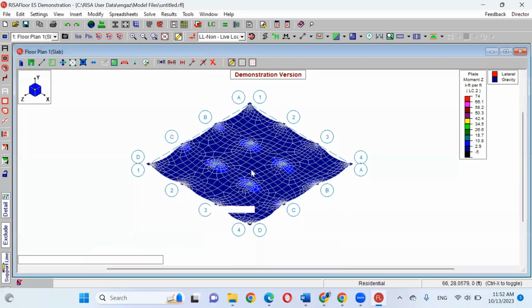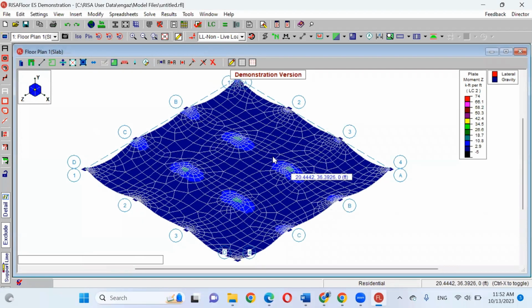Okay, you can see here the deflection of your slab. This is the deformation. Can you see the original position of your slab? It is this line. We have deflection coming down. The slab went down. At your supports, at the columns, we don't have deformation, still the same. But in between, the slab went down a little bit. You can read the values. It's in the range between 2.9 inch and 5 inch.